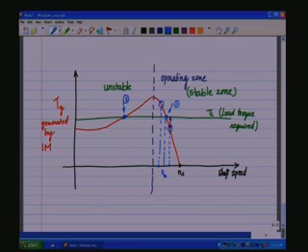So therefore, even if there is a slight deviation in the operating point, the characteristic is such that it pulls it back to the operating point to supply the load. Therefore, anywhere along this line here, what I am showing, that is in the operating zone portion of the line, they are all stable. Any deviations can be pulled back into the normal operating point for a given load torque.